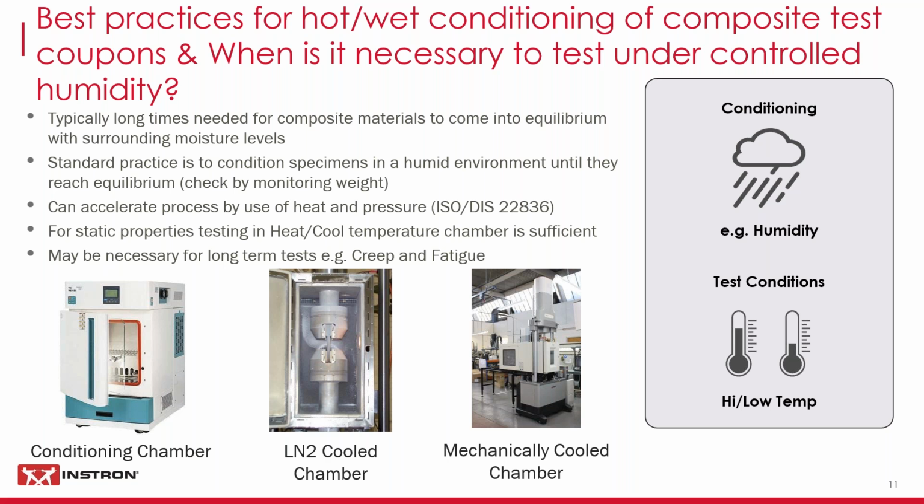When it comes to actually testing the static properties of a conditioned specimen, it's generally entirely possible to just use a simple heat-cool chamber. There's no need to actually reproduce the humid environment when you're doing the static testing, because the timescales associated with losing the moisture are the same as they would be for absorbing it. So the coupons are not going to lose significant amounts of moisture over the duration of the tensile test, even at temperature.